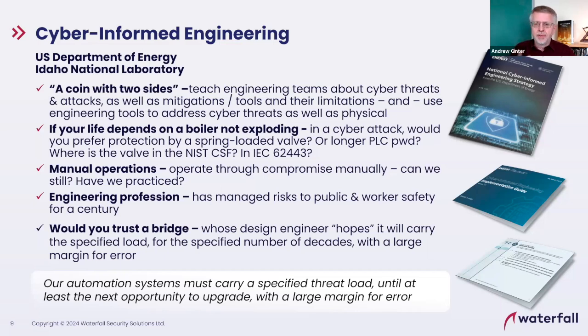What does that mean? If your life depends on a boiler not exploding in a large power plant, you're the technician responsible for the boiler. You work 8 hours a day within the kill radius of a worst-case boiler explosion. How would you prefer to be protected from a cyber attack that overheats the furnace under the boiler? Would you prefer a mechanical valve, where if the steam pressure is too great, it forces a piece of steel against a spring, the spring deforms, the steam escapes, there's no explosion? Or would you prefer a longer password on the PLC controlling the furnace? Most of us would prefer the mechanical valve.